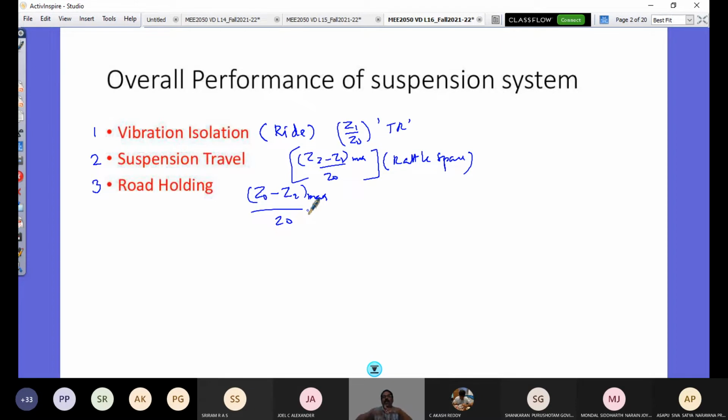When you drive your vehicle, about that it is going to vibrate. So when it is vibrating, the tire deflection is the measure of your contact patch. If the tire deflection becomes zero, what will happen? There is the point of detaching from the road surface. That means there is less load acting on that particular wheel, which is primarily required to cater your traction or lateral forces, and they are going to be less. So that is very less, then poor handling would happen.